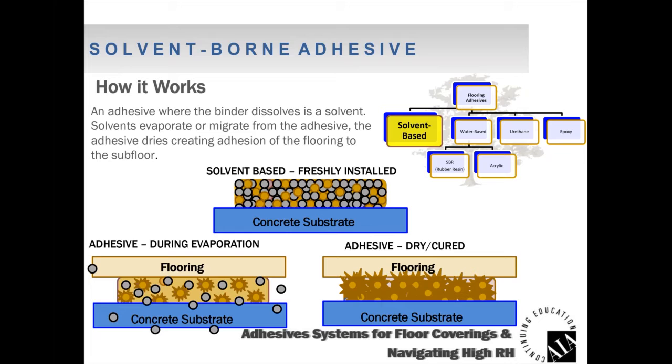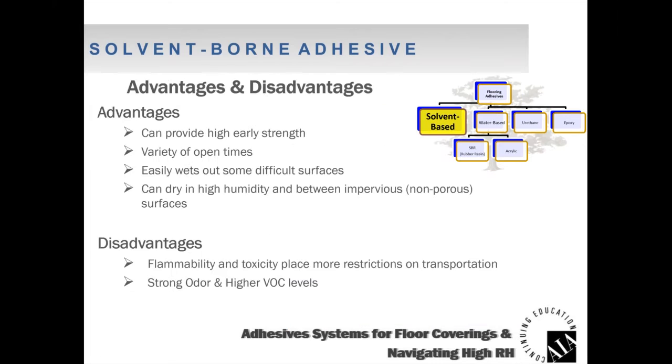There's a variety of different solvents out there, but the solvent is the carrier that gets the polymer, the binder, to the floor, or the wall if it was a wall adhesive. And then once that solvent flashes off, the polymer can coalesce and bind the floor covering to the substrate. Okay, that's how that works.